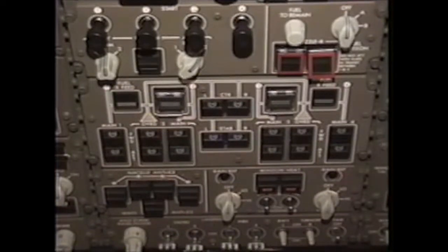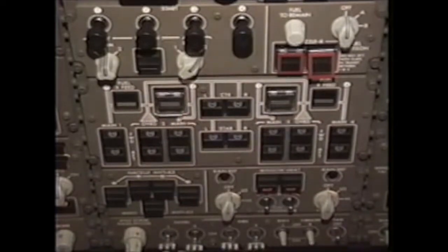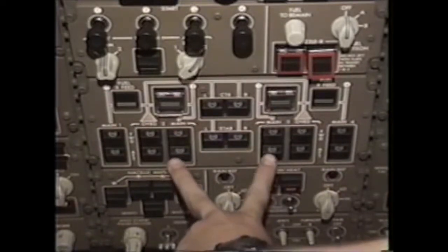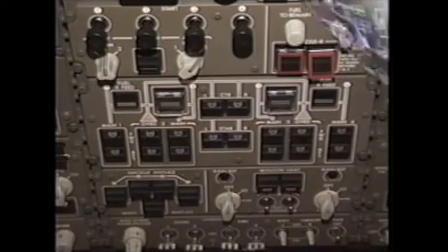Whenever the aircraft is on the ground and the trailing edge flaps are set to position 10 or 20, crossfeed valves 2 and 3 will automatically close. As a result, the center wing override jettison pumps will continue to feed engines 1 and 4. However, the main tank boost pumps in tanks 2 and 3 will then feed their respective engine. This can be verified by bringing up the fuel synoptic.